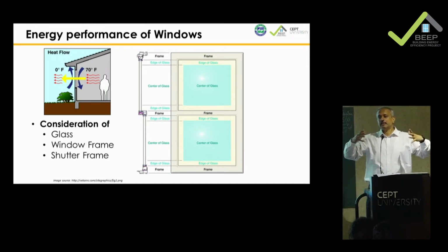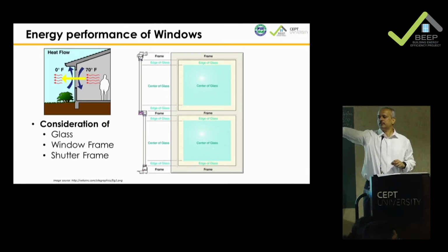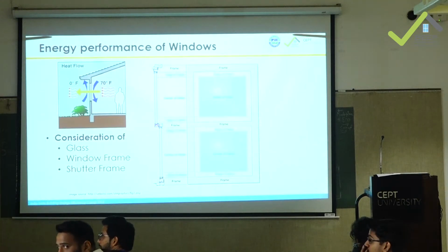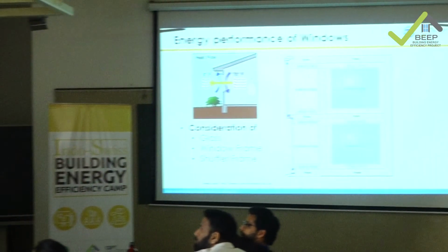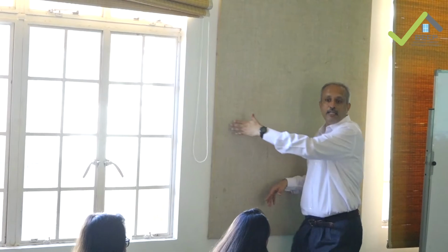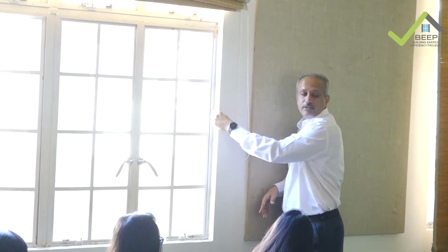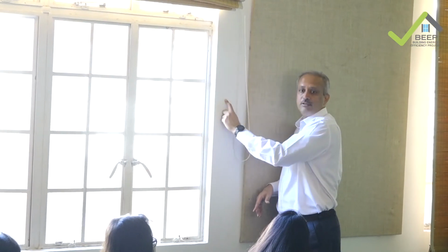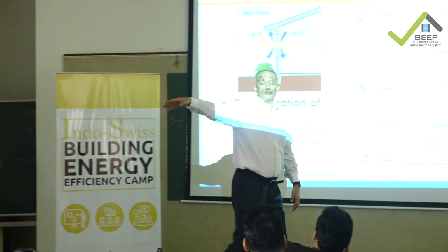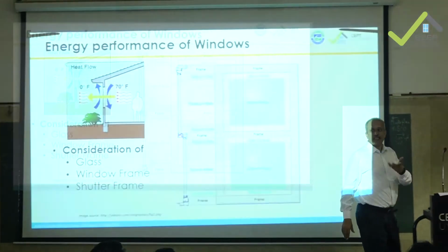So, just imagine that I have that wall junction. So heat transfer here, and that's what we call the edge effect. Here the edge effect is much lesser than the edge effect here. Okay, this guy is giving it to this guy, giving it to this, sometimes this guy is also giving it to this. So it becomes a very complex situation, three-dimensional heat transfer, and many things happen at one point in time. And what I am talking about is only U value. What will happen to the radiation and convection, nobody knows.